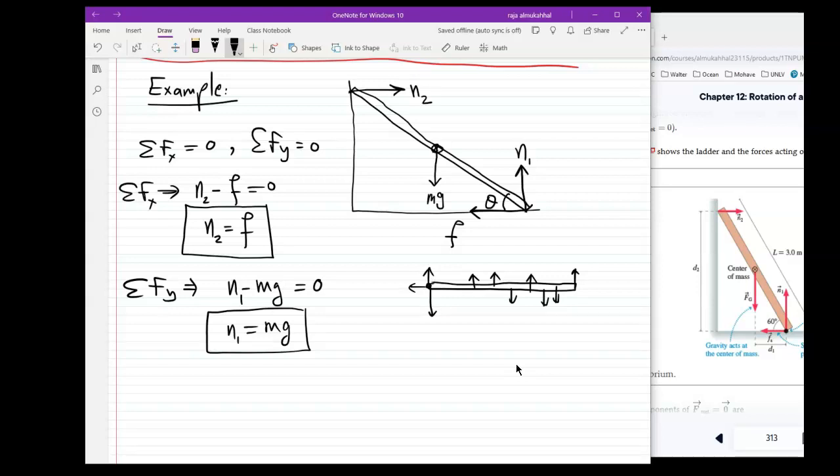And let's say at the point here I have maybe 3 vectors or something like that, and I want to take the torque. Of course, I'm exaggerating the number of forces here. When you have something like that, always take the torque about a point where there are too many vectors coming out of it. Why is that? Because the moment arm here would be 0, right? Moment arm is how far the vector is from the point. Well, it's on the point, so 0. So if those 3 are unknown, you don't have to deal with them, because they contribute 0 torque. That's what I'm trying to say.